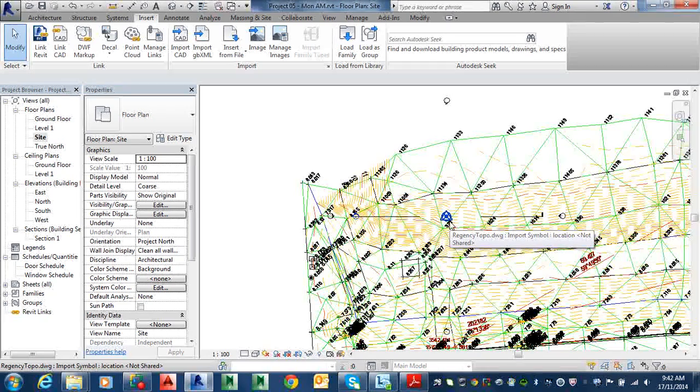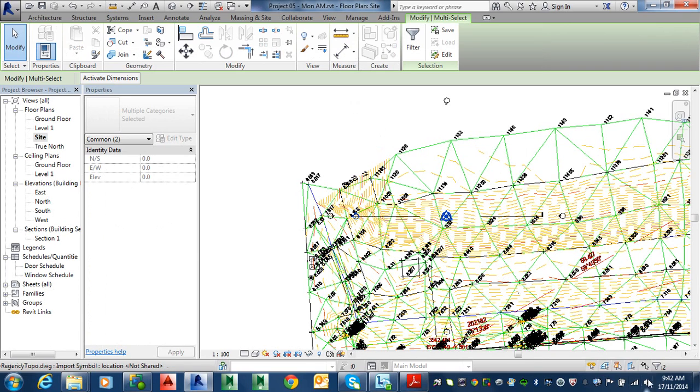All right, so the next thing it says is to pick up the survey point, not the project base point, but the survey point, and move it to the PSM. So we know how to do that because we've done it before with the filter command. So basically, all we've got to do is highlight all this, and it picks up a whole lot of stuff. I picked up two things in this instance, which is good.